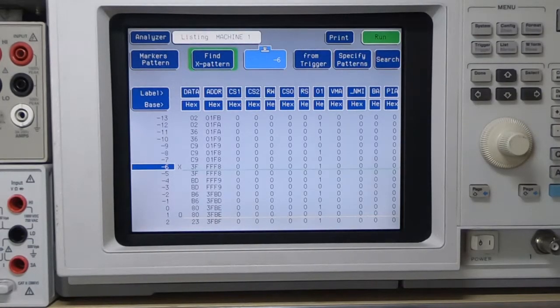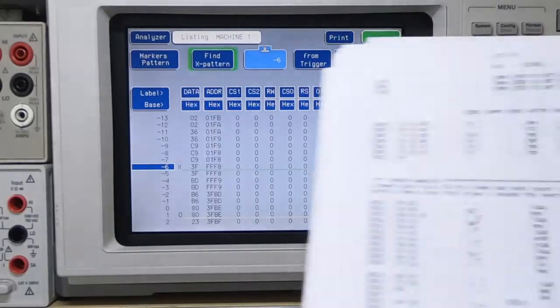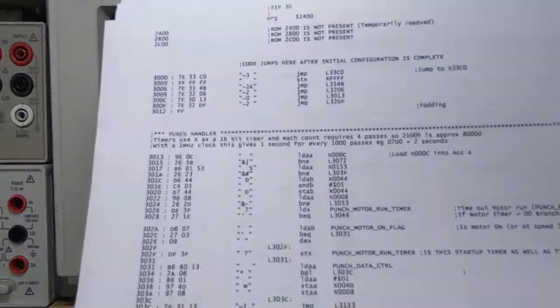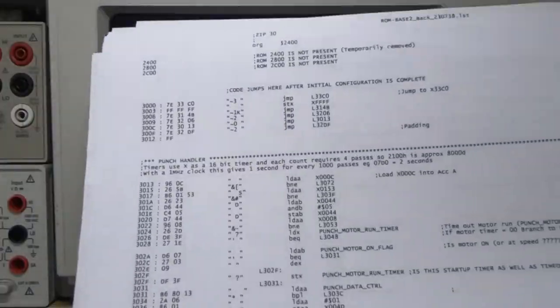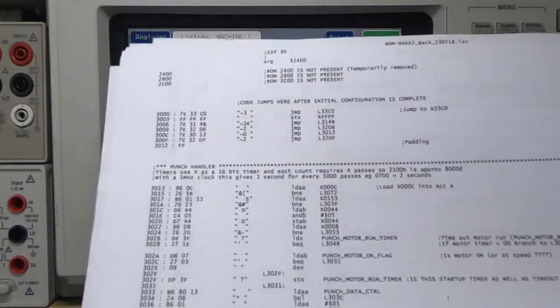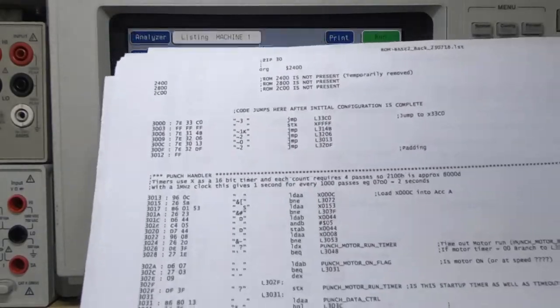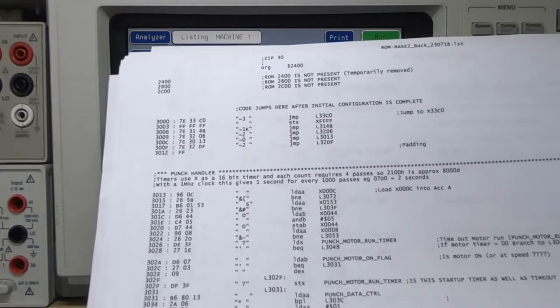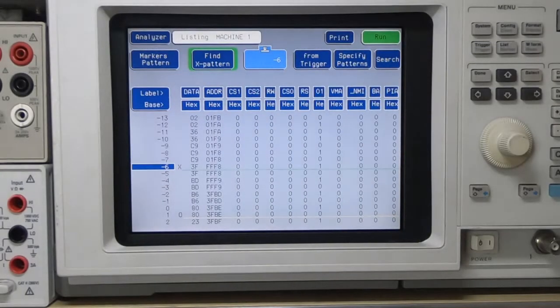But as I said, the main disadvantage is that you just get repetitions of blocks of code, and what I wanted to be able to properly examine the operation of this machine was a single printed listing that I could reference and see how the software worked in its entirety. So that's the reason why I tend not to use inverse assemblers for this type of work. It's because it's a kind of all or nothing thing where I need the entire listing to be able to make sense of what's going on and where the fault I'm looking for may lie.